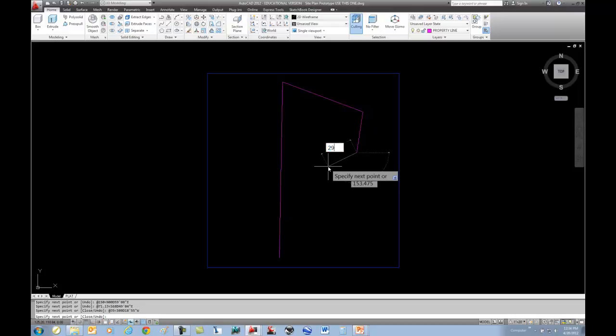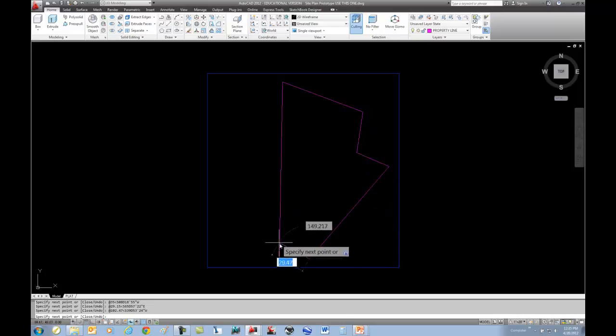And then we've got 29.15 less than, south 65 degrees, 57 minutes, 22 seconds east. That produces that. Then we have 102.47 less than, south 39 degrees, 53 minutes, 24 seconds west. And then the final one, what you don't want to do is snap to endpoint.